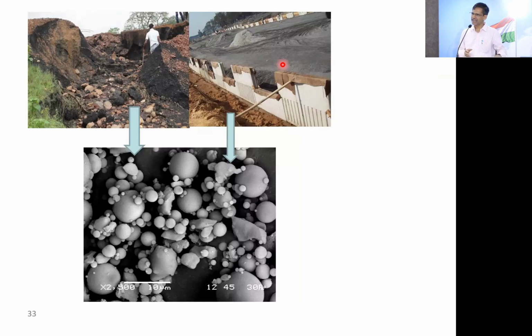So it is spherical. It has no angular particles, and my design of friction simply says that angular particles give better friction. And my RE1, reinforced earthwork, for which you do stability analysis, is based on the principle of friction. So that never tears out. The strips you are now designing hardly break.